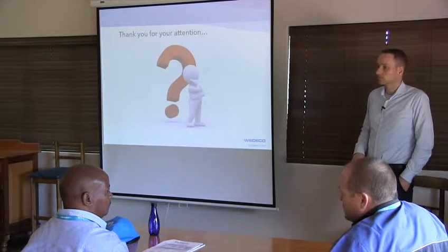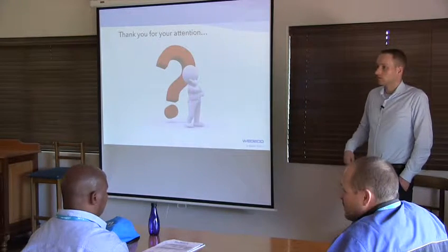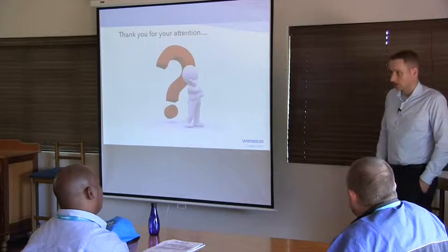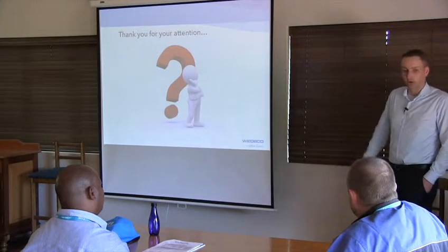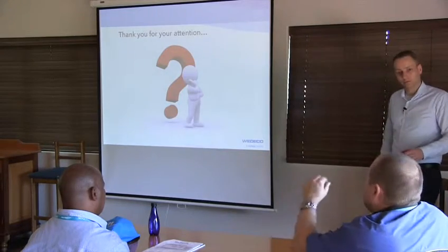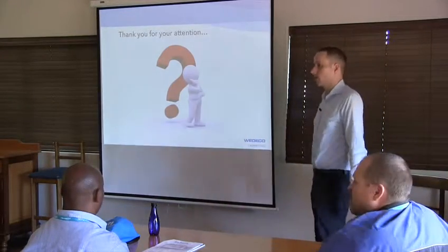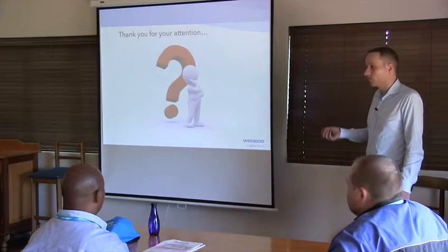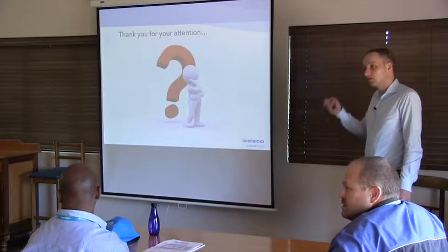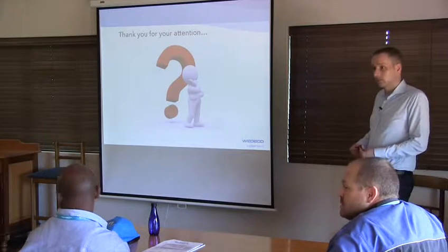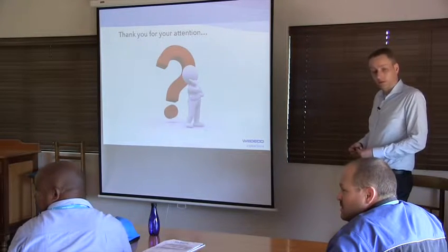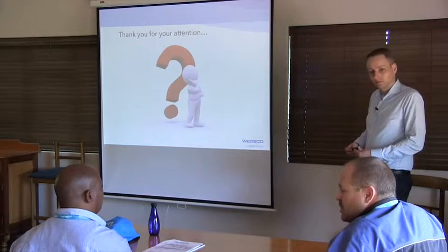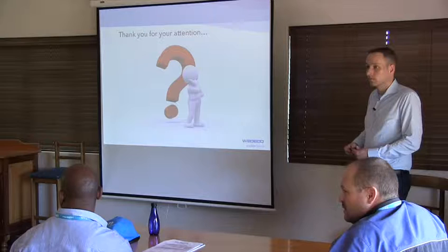Isn't that part of all the UV? For the Spectrum series and upwards, definitely it's standard. I'm talking about the little ones, the household ones. The household ones do come with a control box, and that control box doesn't put the light on unless there's flow through the unit. You have to have flow before the UV starts, because you have to have movement over your lamp.